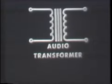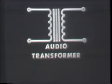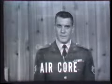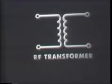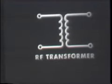Like the power transformer, the audio transformer, too, is usually constructed with an iron core. At frequencies above 20,000 cycles per second, the RF transformer comes into use. At these frequencies, hysteresis and eddy current losses in an iron core become so great they have to be prevented. Therefore, RF transformers generally have an air core. The schematic symbol for an RF transformer, then, is easily identified by there being no vertical lines between the primary and the secondary coils.